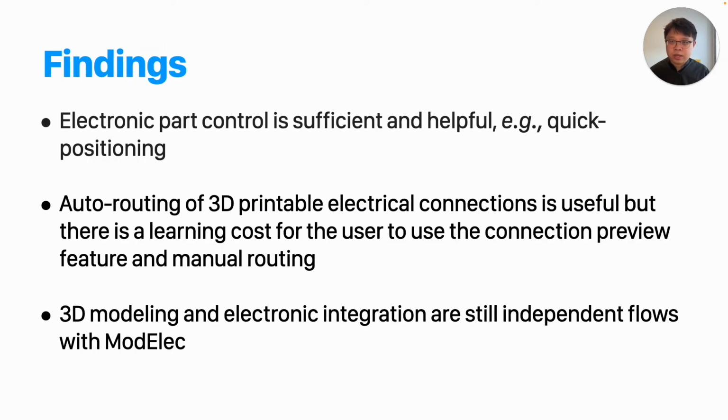Here are some takeaways. Electronic part control is sufficient and helpful, especially the quick positioning feature. There's a learning curve for the logic connection preview and manual tracing. The 3D modeling and electronic integration are still 2 independent flows with ModElec.